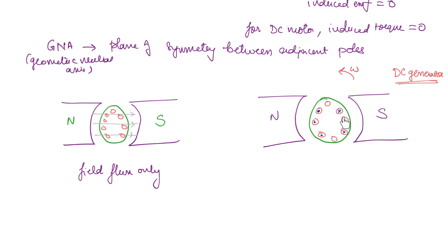Now due to each of these conductors, if you draw the magnetic field, right? For example, if you take one conductor whose current is going into the plane, then what will be the direction here? It is going to be in the clockwise sense. Similarly, if you take a conductor where the current is coming out of the plane, then here it is going to be in the counterclockwise sense. So for each of these there is going to be individual magnetic field lines, but when you add up all of these magnetic field lines, then you are going to get a magnetic flux which is something like this.